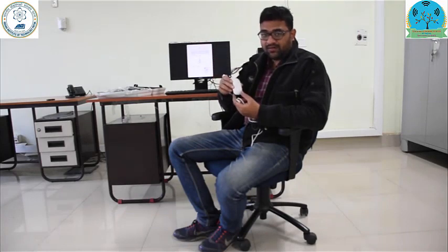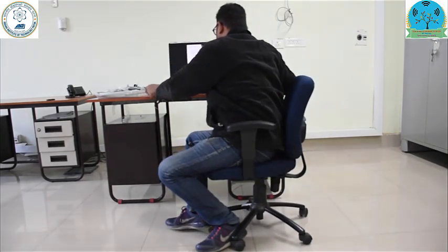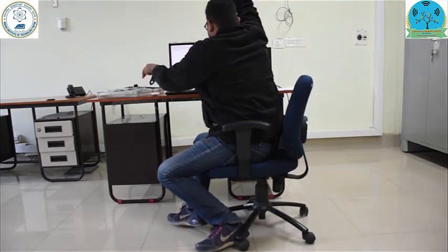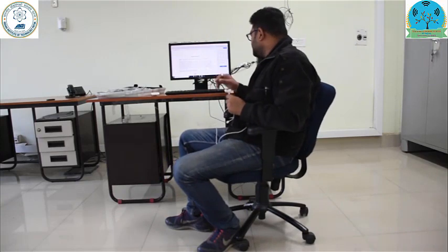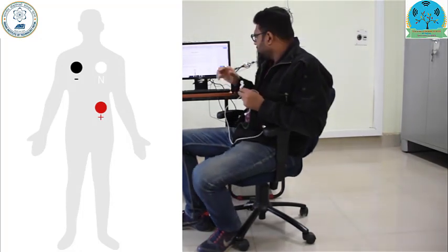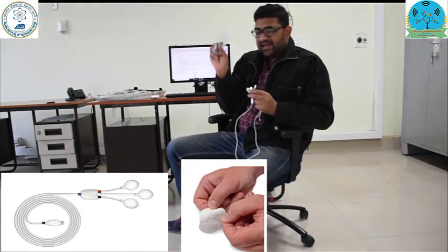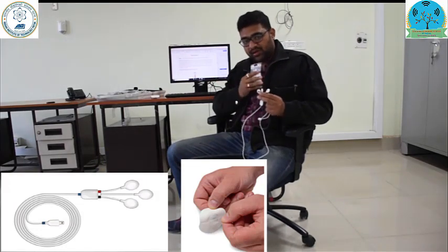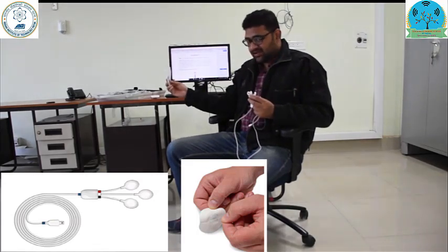Now, to give you an example, first, how do we record the data through biosignal flux? Let us say we want to record the ECG of a person. To measure any ECG activity, we basically need 3 nodes: a positive, a negative, and a neutral node. Now these 3 sensors are used for measuring the ECG using surface electrodes, which are nothing but gels deployed on the human body where the heart is located, and then using our biosignal flux kit microcontroller we can measure the waves and transmit them to a third party.